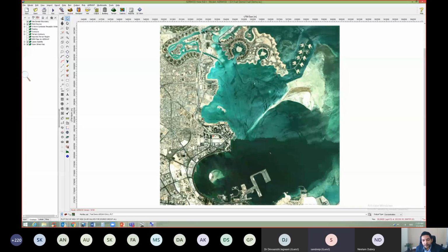They are very well equipped with such software, and in India many consultants are also performing air dispersion modeling using software like AERMOD and CALPUFF. So yes, this is also a requirement in India. I think the category A projects are being handled by the central Ministry of Environment and Forest. They ask for air quality impact assessment done through software like AERMOD.